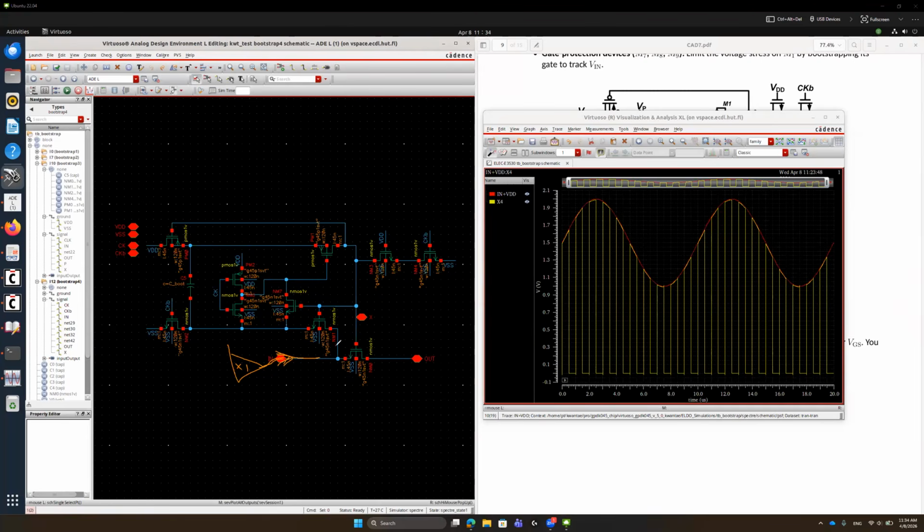Then this one is somehow connected to the bootstrapping capacitor, that means during the tracking phase it is equivalently the same situation as a circuit that has a buffer with an output capacitor added, as C equal to, let's say, 1 picofarad. So that means our gm over C will go down. That gm over C means the gain bandwidth of this buffer circuit. Then our speed is reduced. So there is some trade-off.